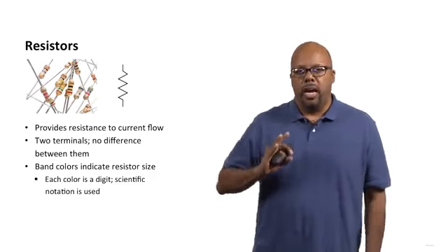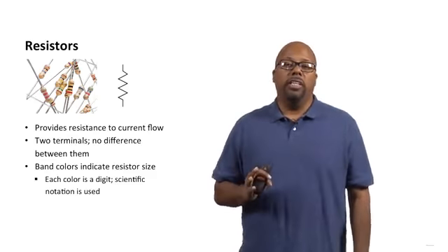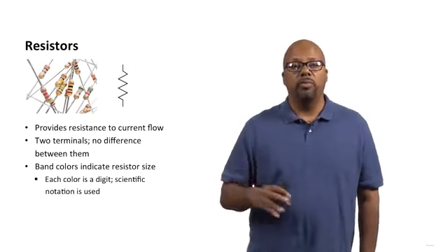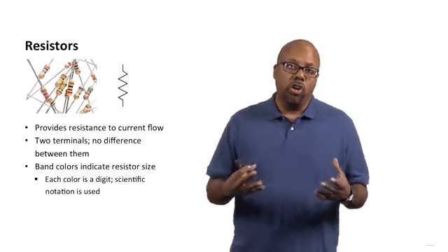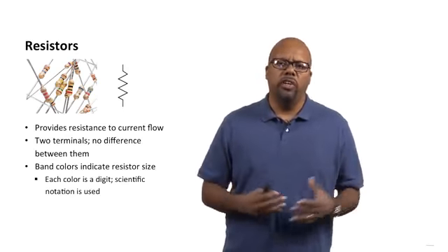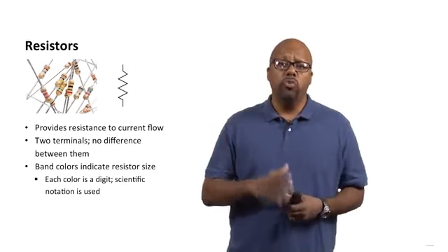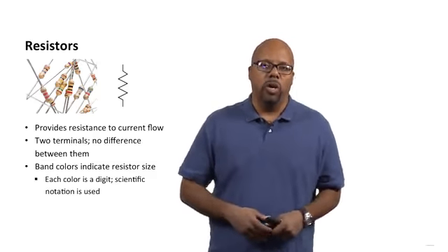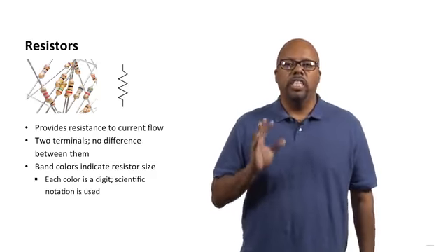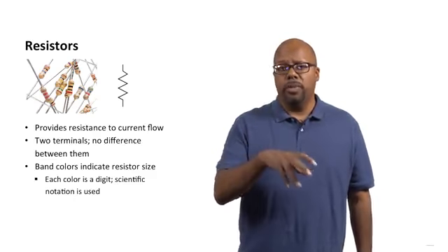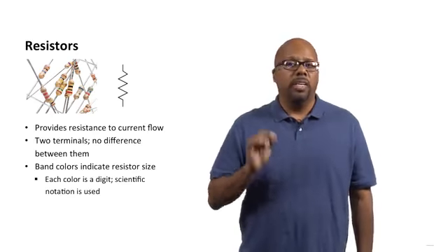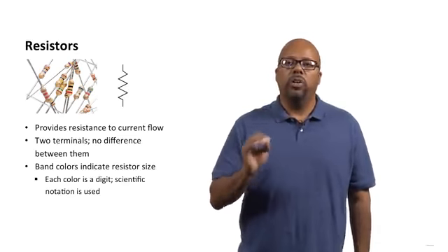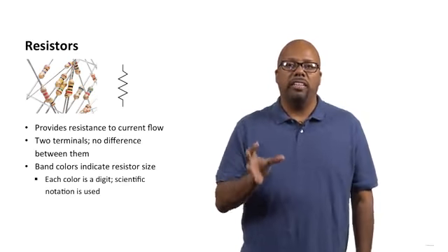Okay. Now, typically, when you do that, you also have what's called a schematic diagram, and we're going to show some of these. You start off usually when you're thinking of a new design. What you do is you draw out a schematic, a drawing of what should be connected to what. This schematic drawing shows what components connect to what terminals, but it doesn't show exact placement. It doesn't show how it will physically look in the real world. It shows, though, how you expect it to be connected electrically.